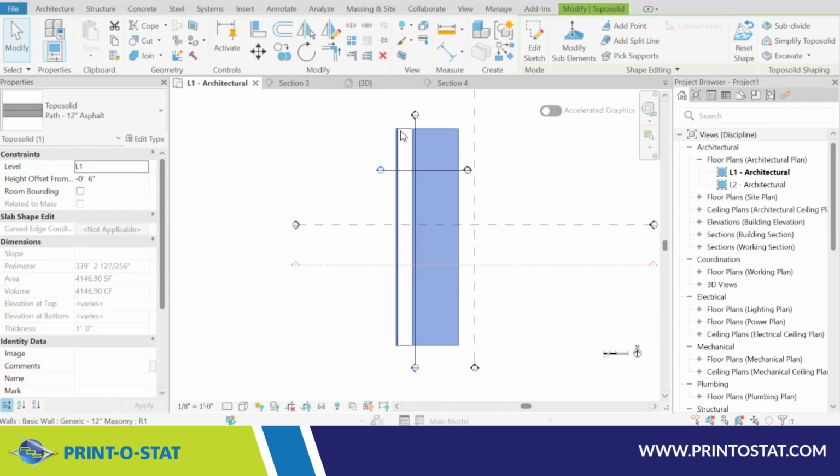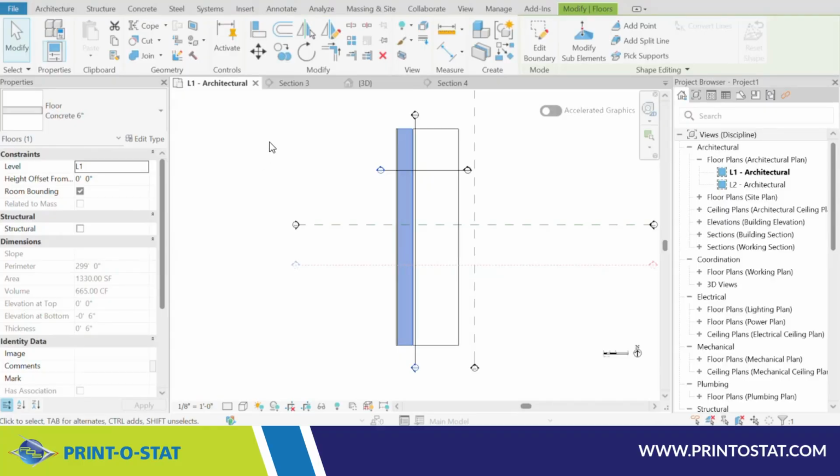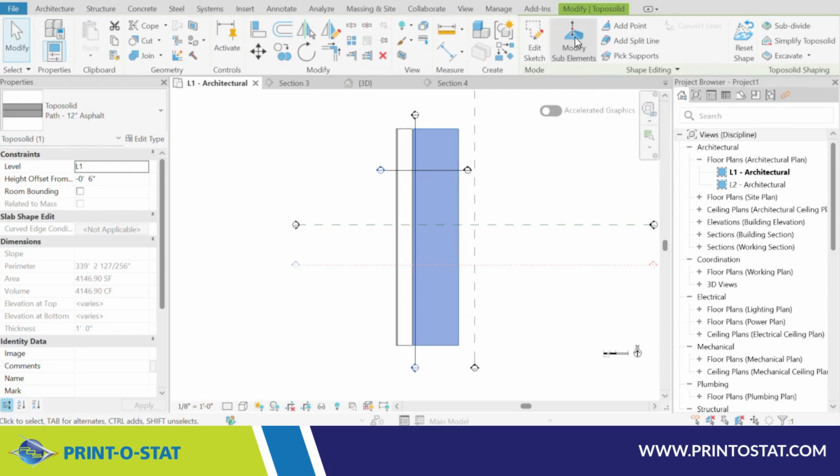This I did right now for the example, all one elevation. This concrete sidewalk is at floor line. The topo, I need to be 6 inches below the top of curb for curb reveal. So I put this topo in. I just drew 4 corners, and that was it. Left it all the same elevation. But there are some points that are below. Let me show you what I mean.